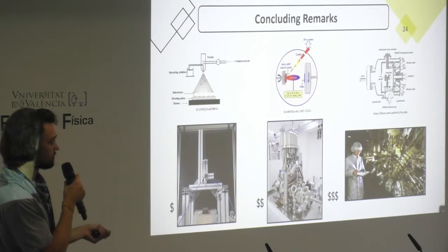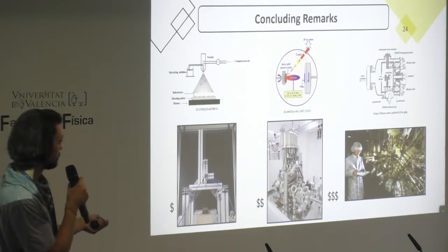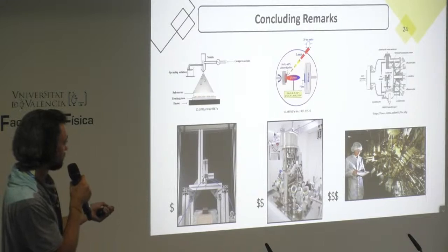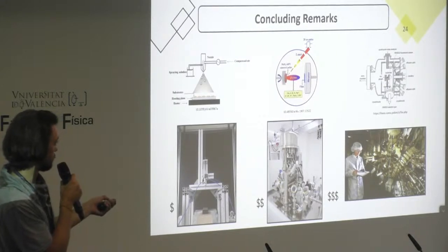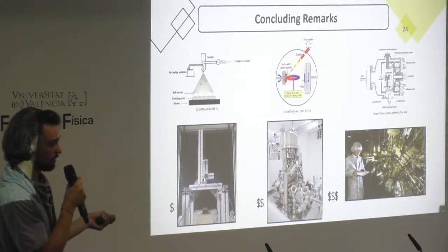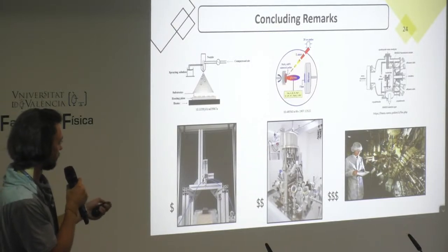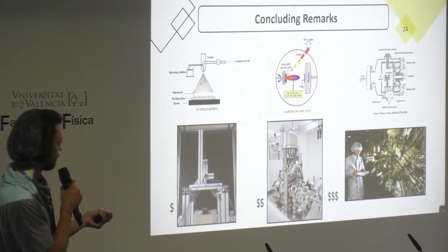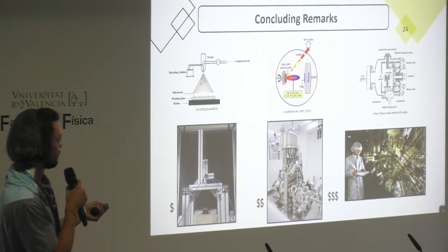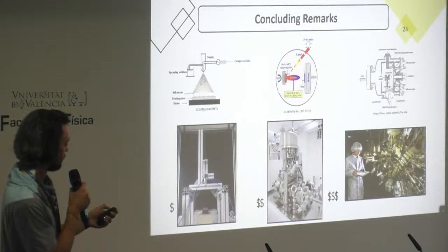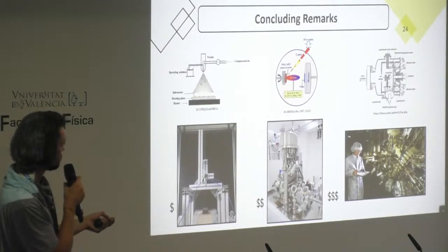This is PLD, which stands for pulsed laser deposition, and this is something similar to what I explained before, but you attack the precursor with a laser, so you get the material from there by making a pulsed laser hit it. So a plasma is created here, so it will end up being deposited on your substrate.